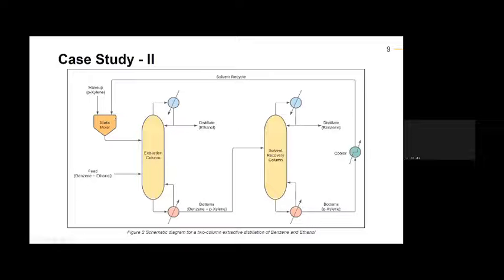And of course, some of the para-xylene is always lost in the process. It might be a part of the benzene or ethanol. That's why we always have to have a very small feed of para-xylene makeup, which can be mixed in a static mixer. This static mixer has the makeup feed and the recycled solvent, and that can be fed into the extraction column.